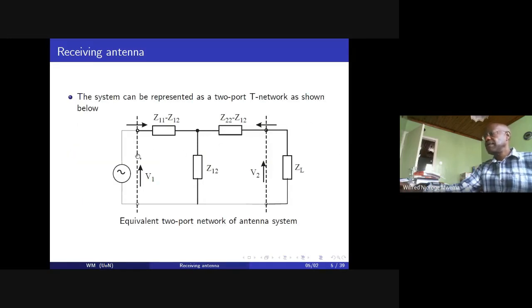You apply the Thevenin's, that is, open circuit the output port, look into the output port and get the value of the impedance that you see when you're looking into the port, and then you get the voltage that will be seen at this point, whatever the voltage at this point, given by that value.